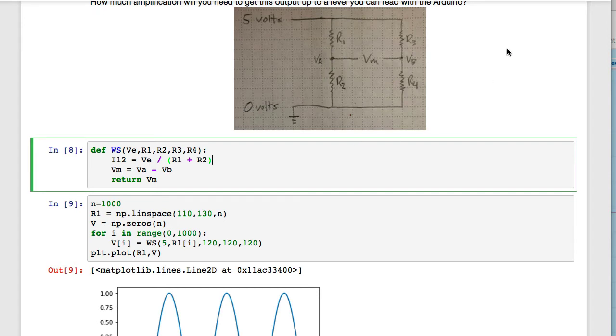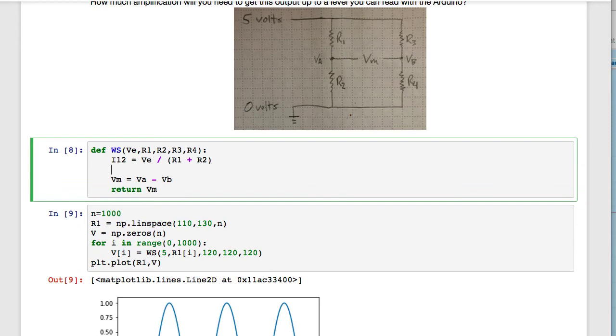So now how could I figure out the voltage at A? Well, Va is not going to be 5 volts, and not 0 volts. It's going to be somewhere in between 5 volts and 0 volts. So it'll be whatever the voltage was up here minus whatever the voltage drop was across there.